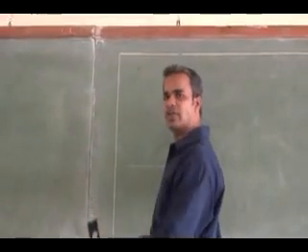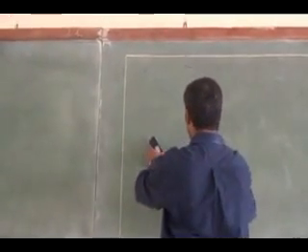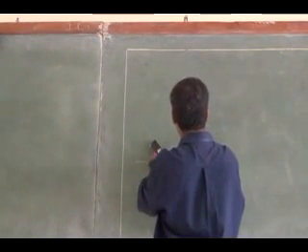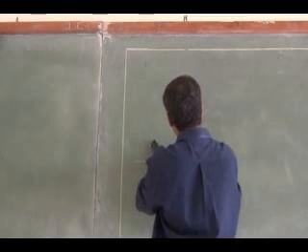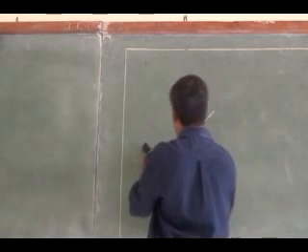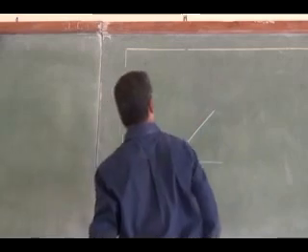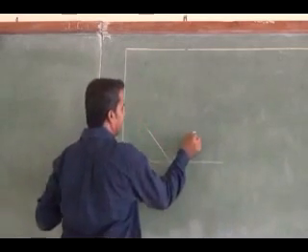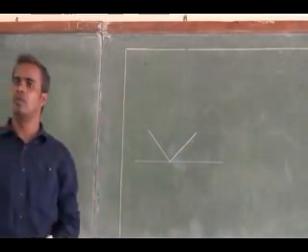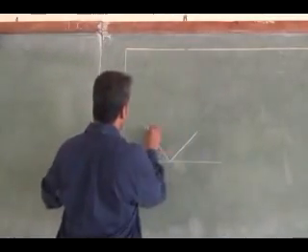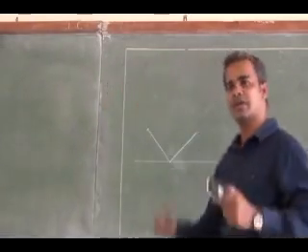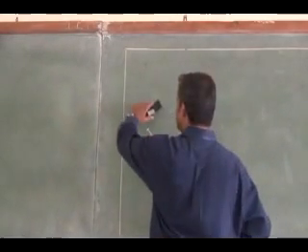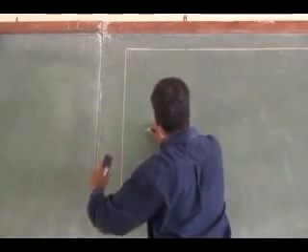You set your drafter to 45 degrees. The drafter will be like this, a small scale and a bigger scale at 45 degrees. Right, this is 45 degrees. Using the two scales of my drafter, I can draw 40 mm, 40 mm. Exactly, in my drafter itself I can mark it. On the same setting I can move my drafter to this end and draw a parallel line.